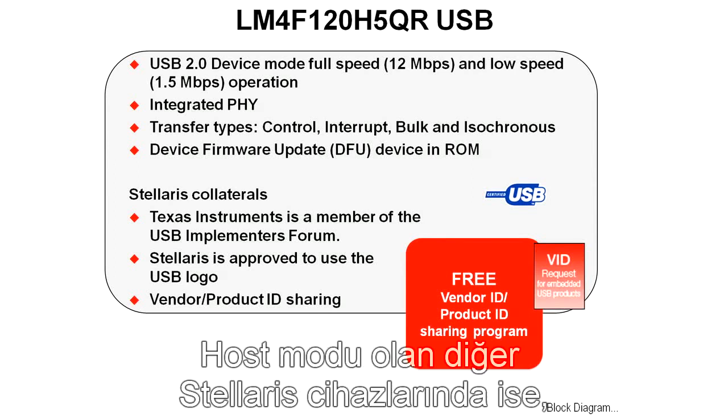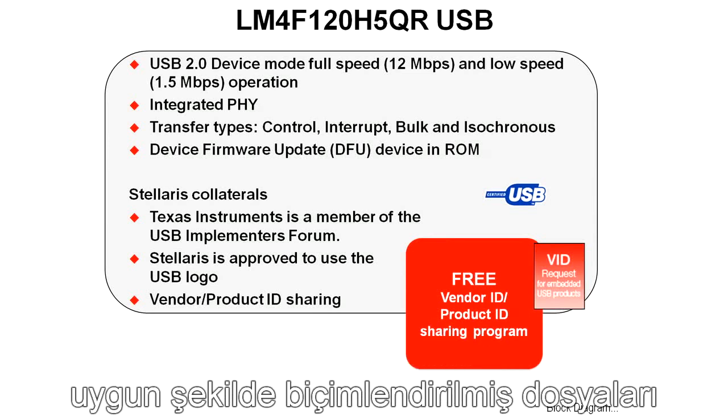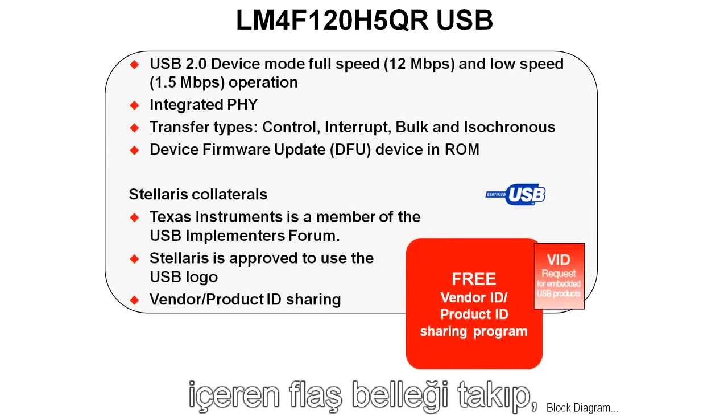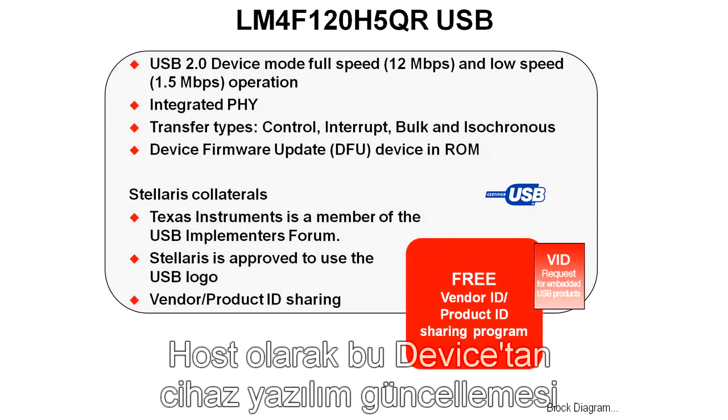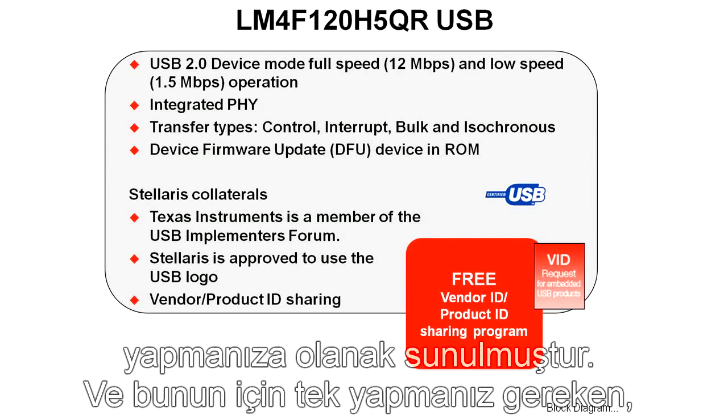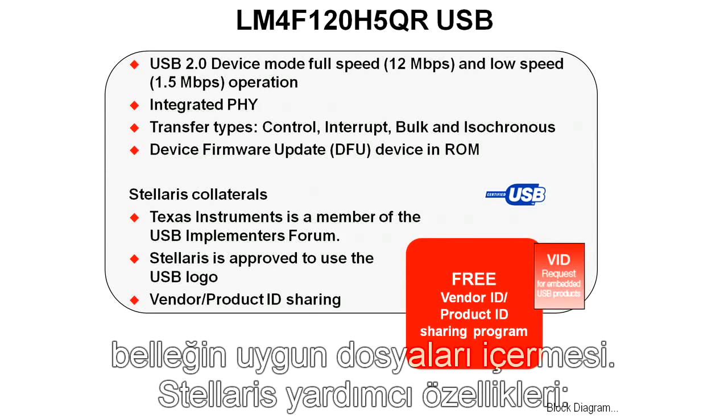On other Stellaris devices that have host mode, you can also plug in, say, a flash drive with the correctly formatted files on it, and it will do a device firmware update from a device as a host. All you have to do, like I said, is have the correct files on it.